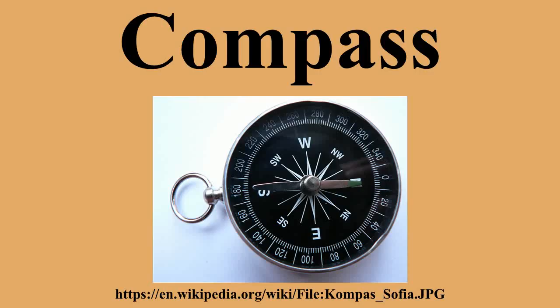Gyrocompass. A gyrocompass is similar to a gyroscope. It is a non-magnetic compass that finds true north by using a fast spinning wheel and friction forces in order to exploit the rotation of the Earth. Gyrocompasses are widely used on ships. They have two main advantages over magnetic compasses. They find true north, i.e., the direction of Earth's rotational axis, as opposed to magnetic north. They are not affected by ferromagnetic metal in a ship's hull.